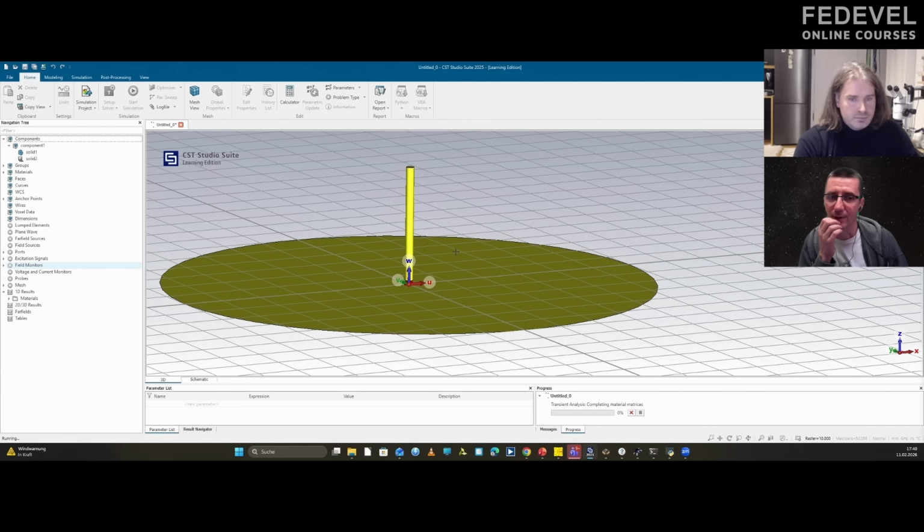But you know what was interesting? I think when we were fine-tuning the antenna, when you have to adjust, for example, the impedance of the antenna, you will add a capacitor or inductor. You also may move it a little bit again. You mean to match the antenna here? Yeah, when you match it, then you can also shift it again a little bit.